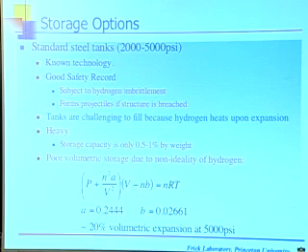There is, for example, the steel tank that is embedded in the ceiling of the chemistry laboratories at Harvard, because some graduate student many years ago foolishly decided to transport a tank without taking the regulator off and putting the cap on, and it dropped, and the regulator broke off, and there was a missile-type effect, which fortunately missed everybody, but the tank ended up embedded in the ceiling, and they decided they would leave that tank there as a reminder to all future graduate students that when you move a tank, you better not have a regulator on it. So good safety record, assuming you follow the rules. That is, the weak link in any tank is the regulator.